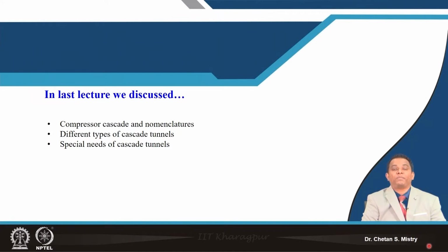But at the same time it has its own benefit. As we discussed, the flow on the blade or aerofoil is initially laminar. At about 30 to 40% of the chord, the flow is of transition nature, and later, towards the trailing edge, the flow is turbulent. So what is happening on that blade surface is of our interest.